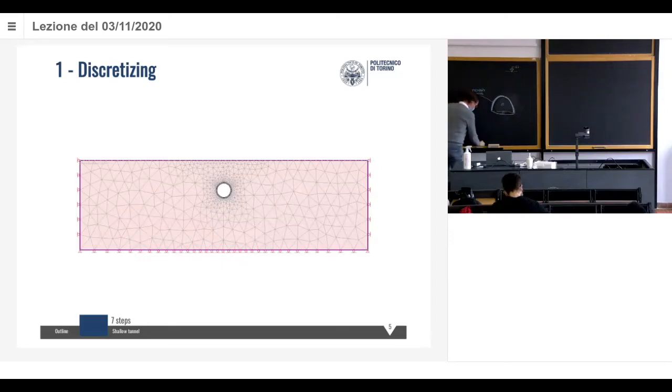Then later on, we are going to install the final lining, which is made like this. Let's do it in one single step. Maybe in a real construction, this is going to be done in more than one step, because maybe we're going to do the inverse arch first, and the straight line and the crown later. And just to simplify, let's say that this is the final lining.